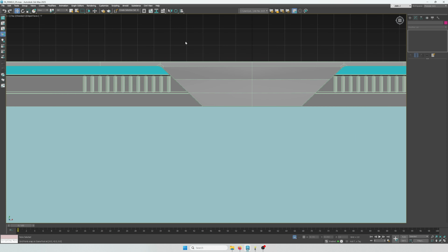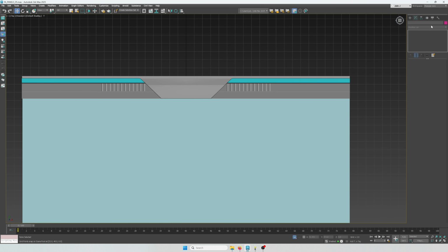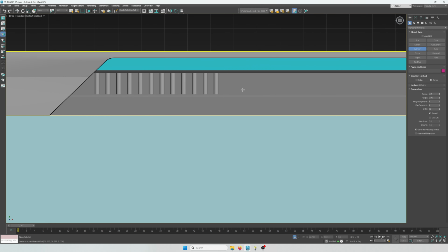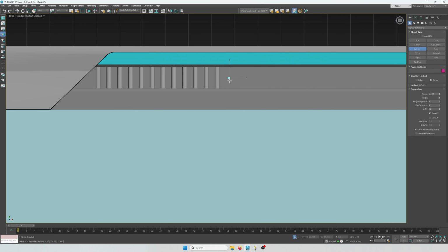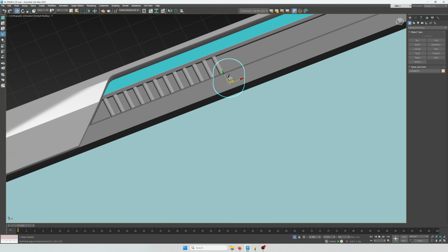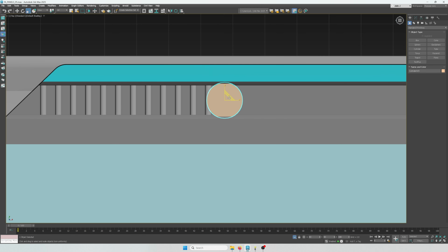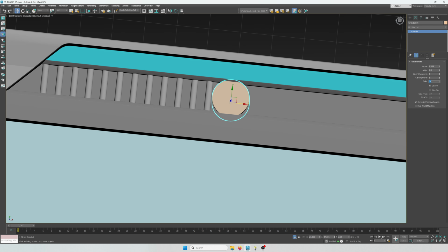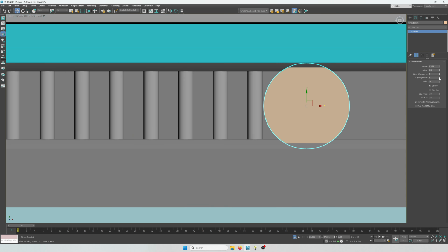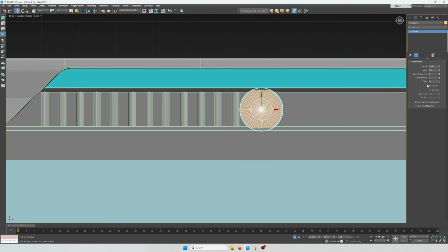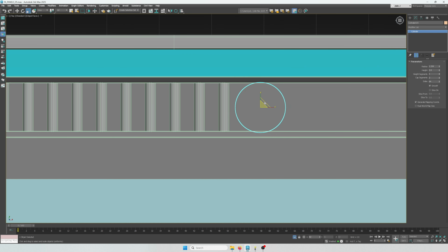I'm not happy with the way these cylinders end abruptly. So I'm thinking of creating a part that caps everything off like it did on our previous part, but in a different way. So let's move a cylinder up and try to center it within the gap. I'm making it so it's really round, so I added 64 sides. It's not going to be using subdivision, so whatever we see here, it's going to show up on the normal.